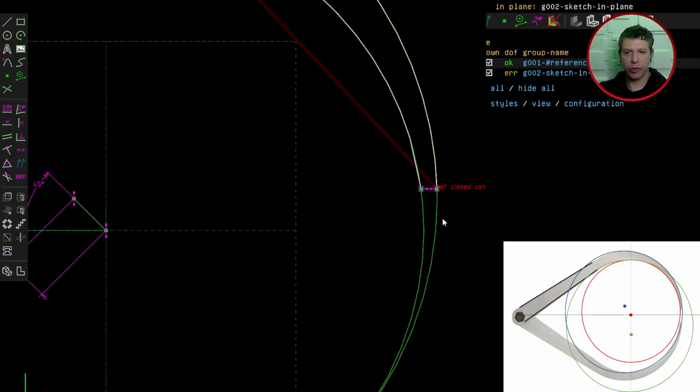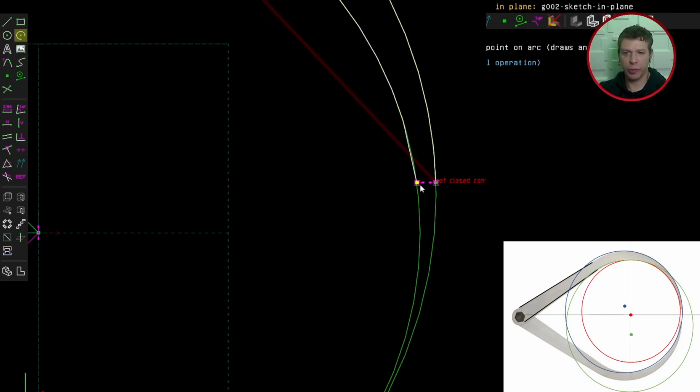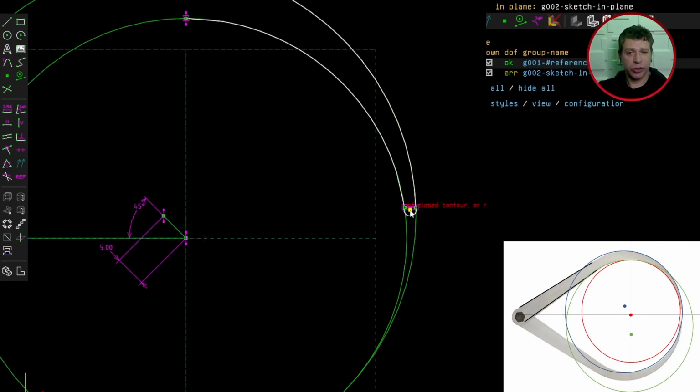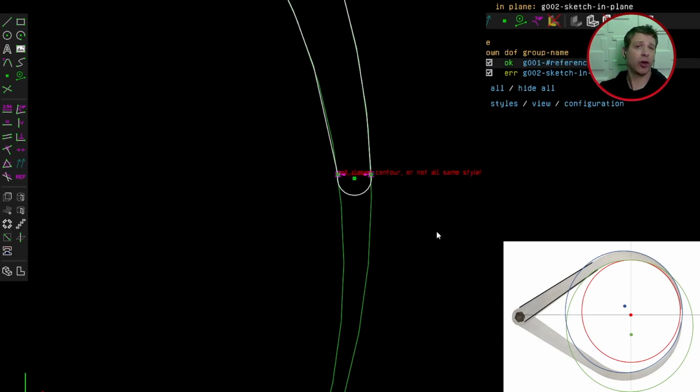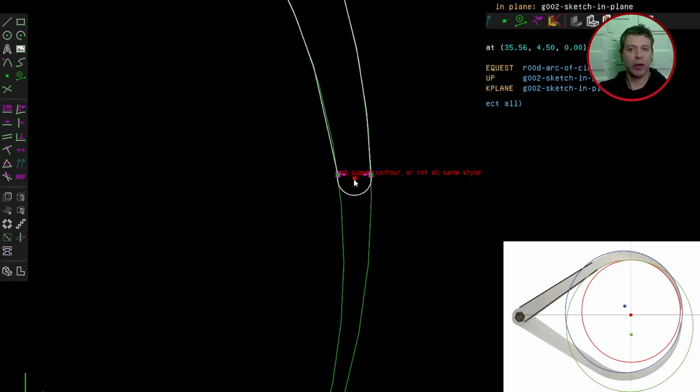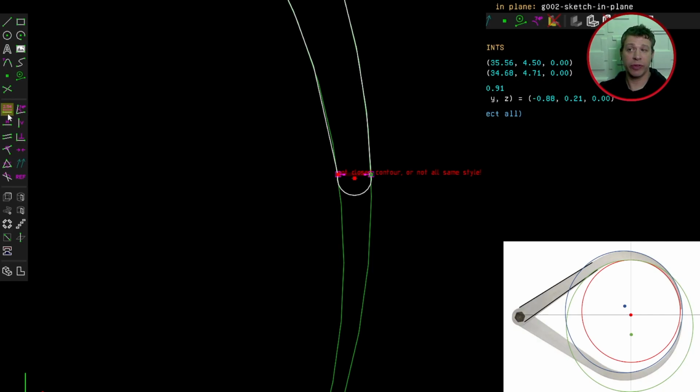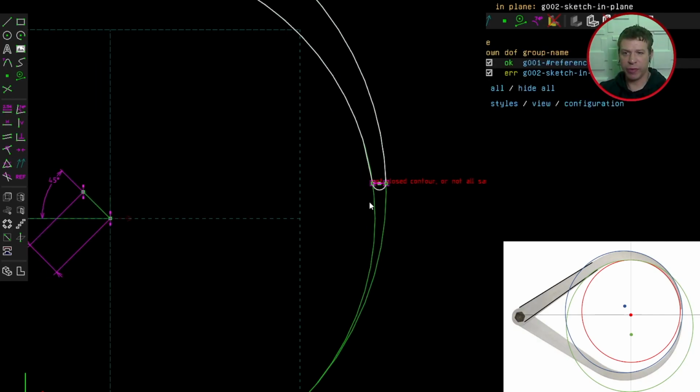It's currently 4. Let's just go with 5. And over here, I can draw another arc just to join those two points together. But now I need to constrain the diameter of this arc. I'm not going to hard code the diameter. I'm going to make this diameter adjustable by constraining the center to be horizontally aligned with one of the outside points there by clicking this button, constrain to be horizontal. Now, if I click and drag this point, you see that the arc will change its diameter, but I can bring it down closer to here to touch this horizontal x-axis.